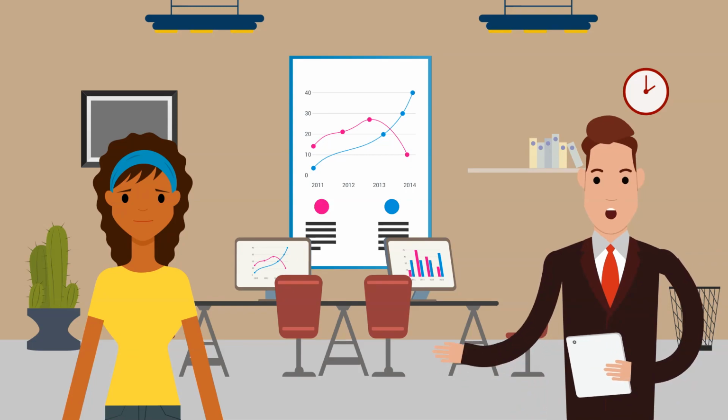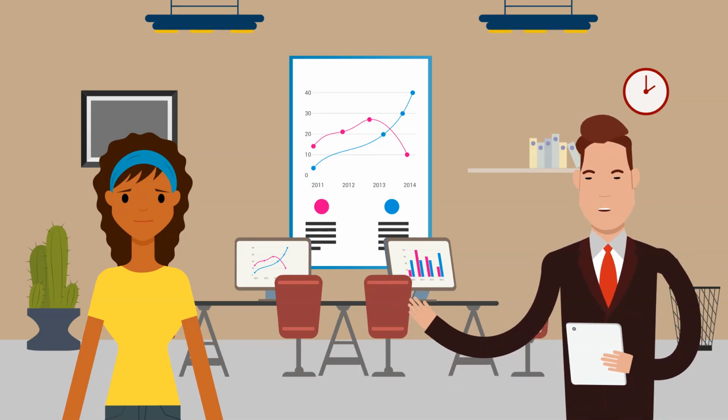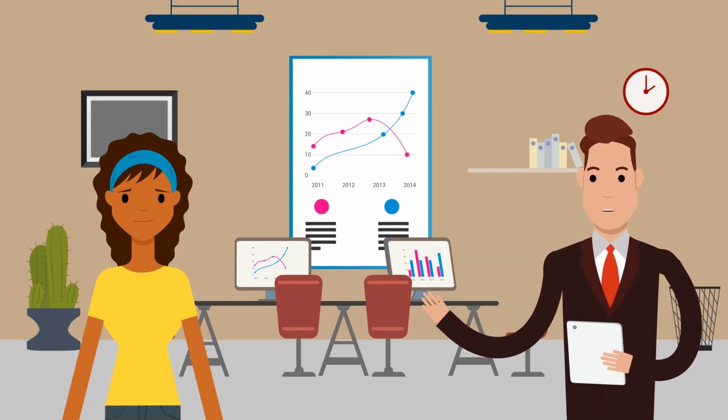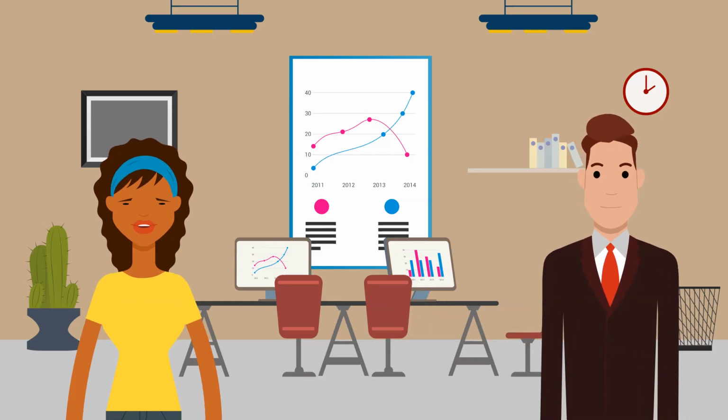We have done many projects using actual flow data and simultaneously created a subjective model of the workspace. If the question is, how accurately does the subjective model compare to actual flow? The answer is typically not very closely. This is why we prefer to use the from to trips or process routing methods as the primary methods to layout creation. We use the subjective method only when there is no flow data or if we have a client that asks for it. That was fascinating.